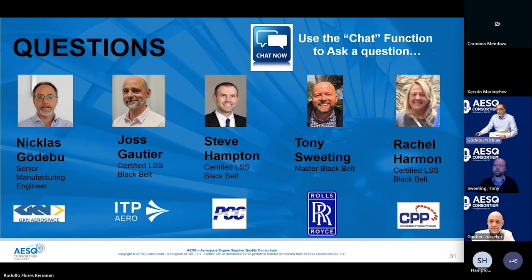Yeah, thank you. So then the next question, quite a long one. Interesting one. We use defect prevention tools, PFMEA, CP, SPC charts for process inputs and outputs to achieve Ppk larger than 2. However, sometimes we are unable to identify special cause from the machining process. Is there a technology which controls, minimizes, identifies machine variation due to material homogeneity or others, cutting force, temperature variation, etc. during the machining process? Please advise.